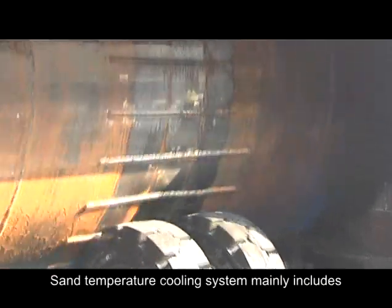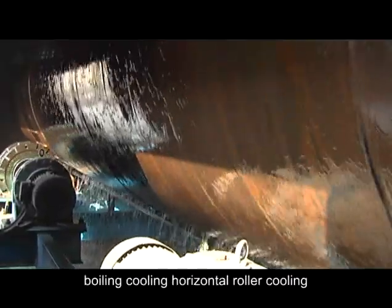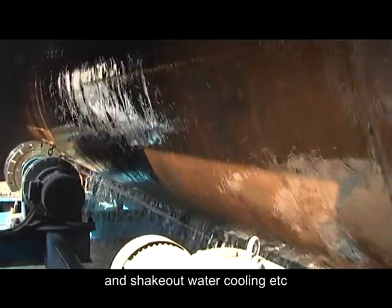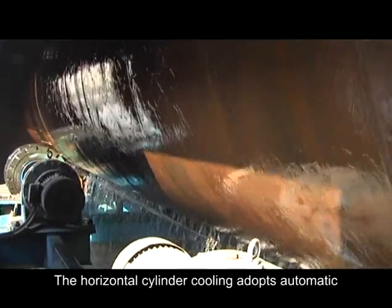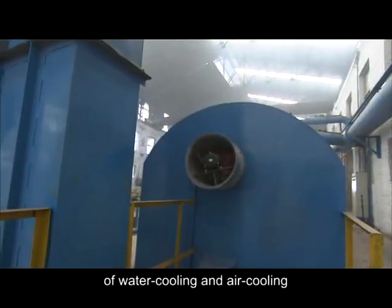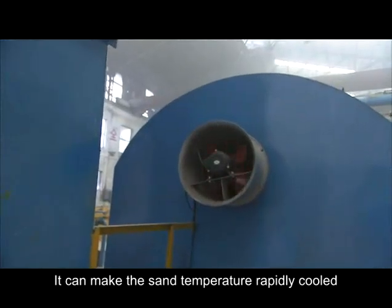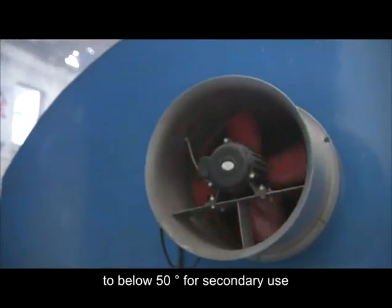Sand temperature cooling system mainly includes boiling cooling, horizontal roller cooling, sand temperature regulator, vertical cooling and shakeout water cooling, etc. The horizontal cylinder cooling adopts automatic sand temperature flow control, with the dual effect of water cooling and air cooling. It can make the sand temperature rapidly cooled to below 50 Celsius degree for secondary use.